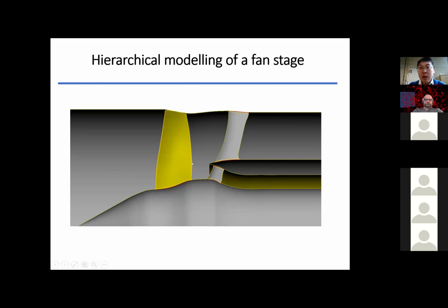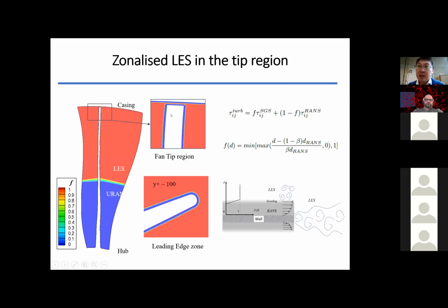And we choose to use the large eddy simulation to model the tip regions because the massive separation happens there, and the wake flow and the tip leakage. So, this region is relatively important because the major loss is generated there, and also the noise is highly generated in these regions. For the downstream stator, for the moment, we just use the low order modeling using the filtered geometry IBM methods.